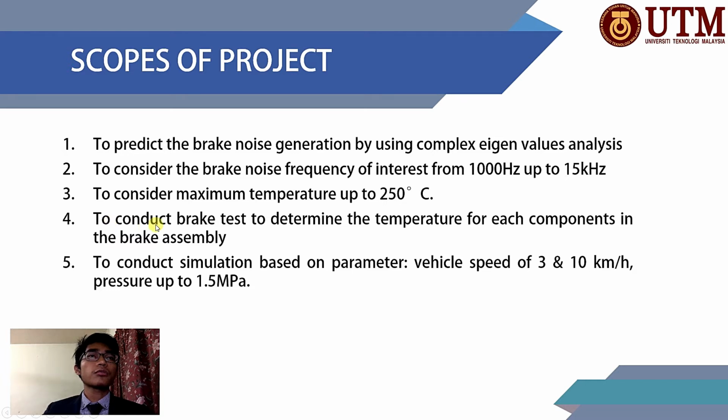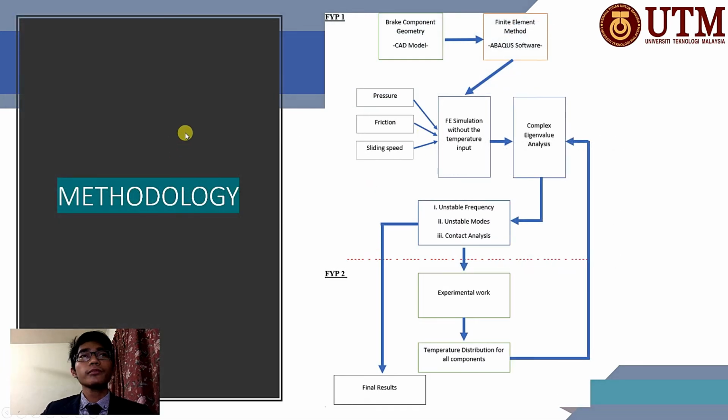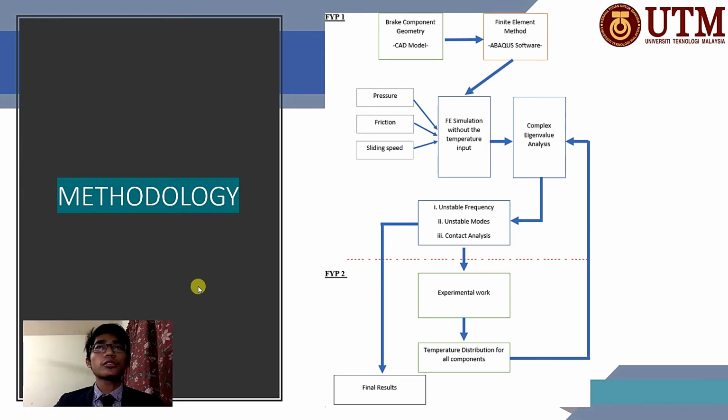The fourth one is to conduct brake tests to determine the temperature for each component in the brake assembly. The fifth one is to conduct simulation based on parameters of vehicle speed of 3 and 10 km per hour and pressure up to 1.5 megapascal. Sorry about that. Okay. Let's go to the methodology.